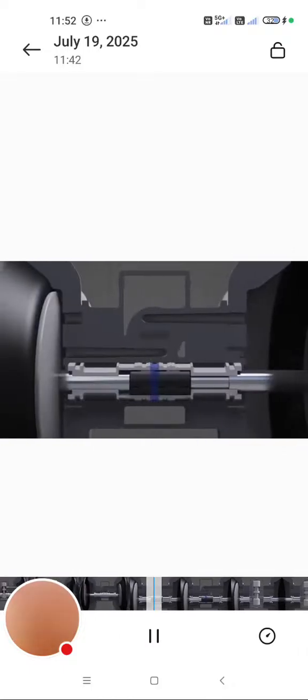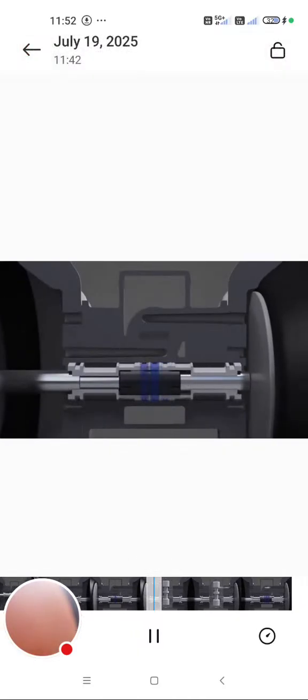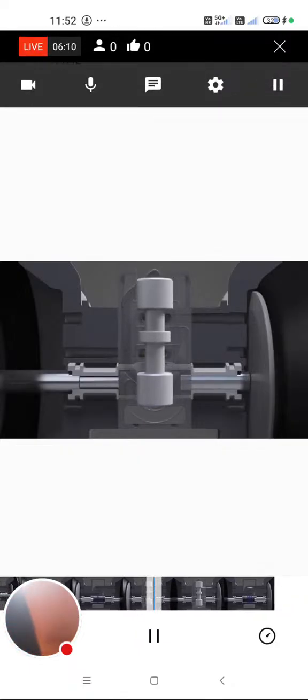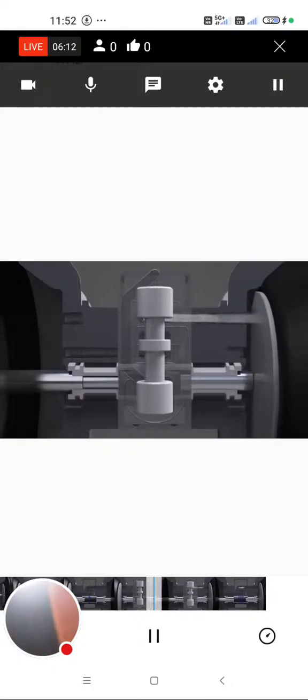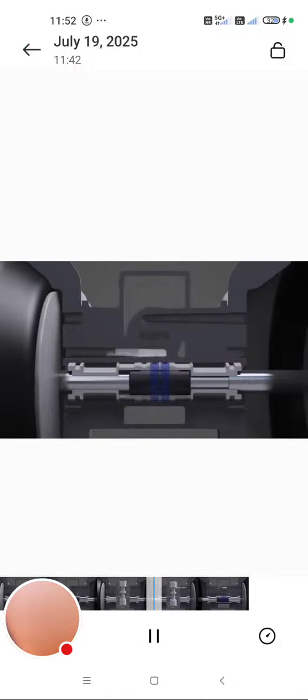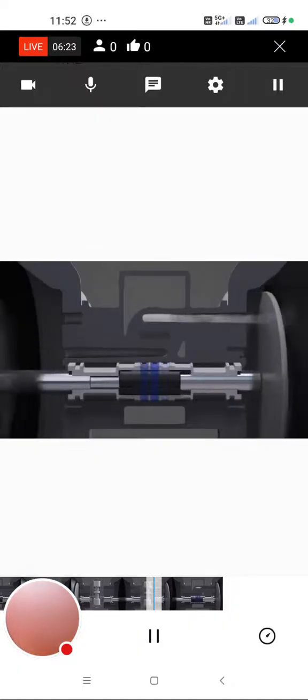Chamber 3 is always under pressure. When the pilot air valve travels far enough to the right, chambers 3 and 4 are connected. This allows the pressurized air to move the main air valve upward. When the pilot valve travels far enough to the left, chamber 3 connects to chamber 2, and the air moves the main air valve downward. This causes the right diaphragm to pressurize and the pilot valve to begin moving right. Throughout the cycle, one side pressurizes as the other exhausts. This process constantly alternates between the pilot and main air valve to create a continuous cycle.